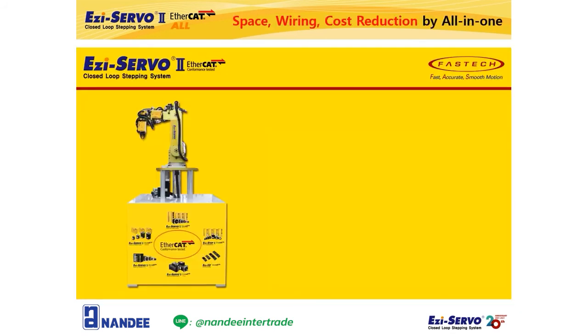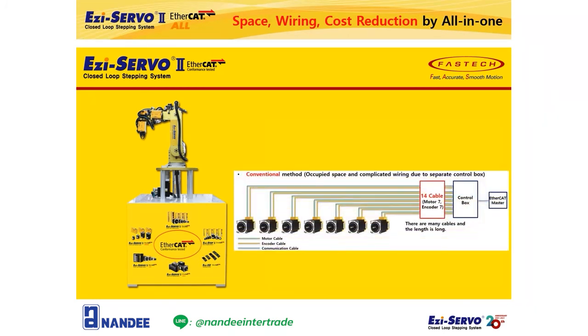Finally, with a 7-axis robot as an example, I will explain space saving, reduced wiring, and cost reduction by Easy Servo 2 EtherCAT All. In general, to operate 7 motors attached to a robot, it requires 7 motor cables and 7 encoder cables. A total of 14 cables have to be connected to the drives installed in the control box, so wiring is not easy. In addition, a separate control box for the drive is required, taking up space.